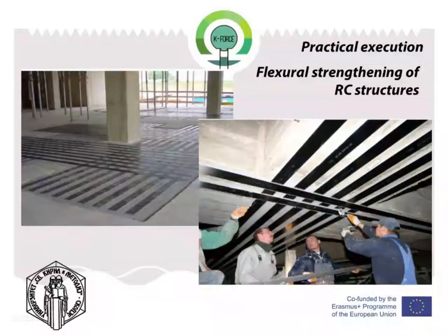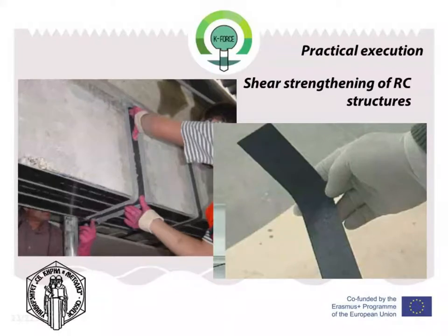Composite materials are used for strengthening wood, masonry and concrete construction in order to increase the bearing capacity of construction under permanent and increased loads caused by earthquakes and environment. The externally bonded FRP reinforcement does not stop existing problems such as steel corrosion. Potential damage mechanisms must be minimized and the concrete should be sound. If needed, the strengthening has to be preceded by concrete repair and internal steel protection techniques.